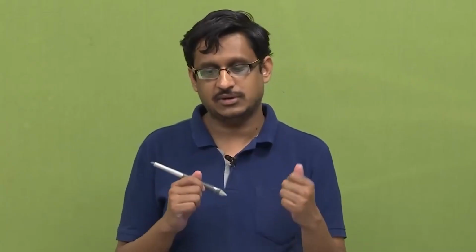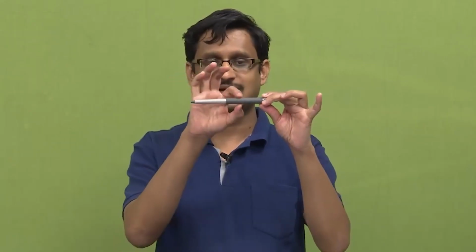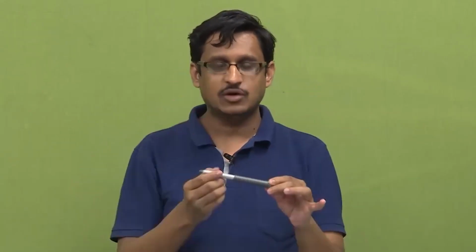How does the optical fiber change the power? Because there is going to be absorption. The optical fiber, if you remember the structure that I showed you in the first module, is something like this. It has a core, it has a cladding, then there are jackets, and all this is not some kind of a hollow tube, they are actually solid materials. They are made out of fused silica, and you know that no material will be completely loss free.